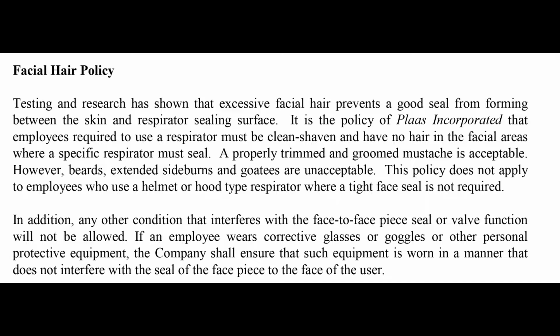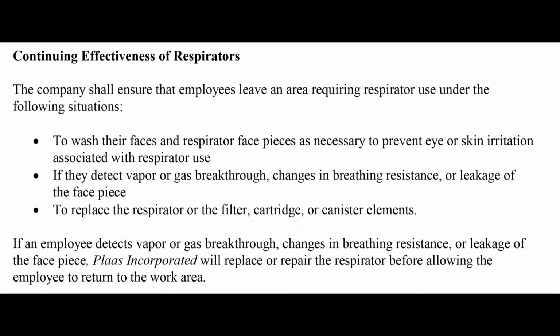This policy does not apply to employees who use a helmet or hood-type respirator where a tight face seal is not required. In addition, any other condition that interferes with the facepiece seal or valve function will not be allowed. If an employee wears corrective glasses or goggles or other personal protective equipment, the company shall ensure that such equipment is worn in a manner that does not interfere with the seal of the facepiece to the face of the user.